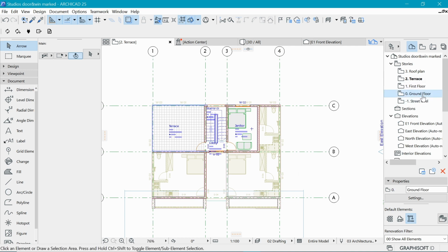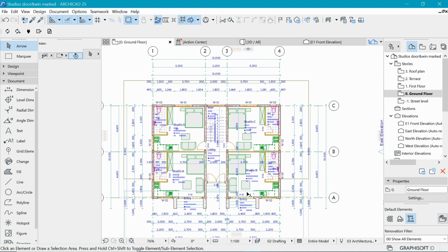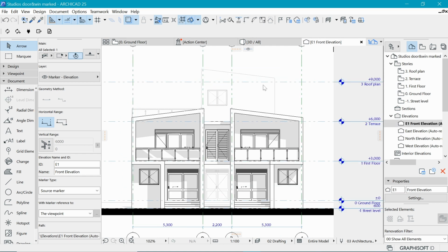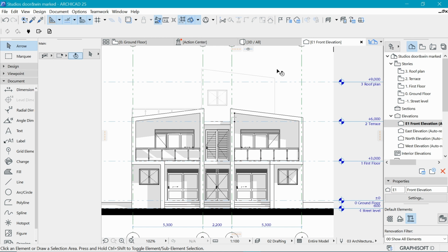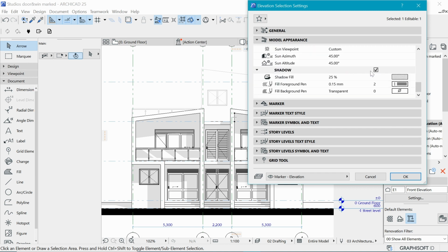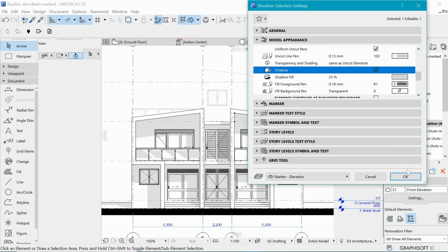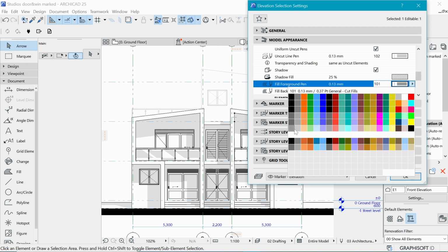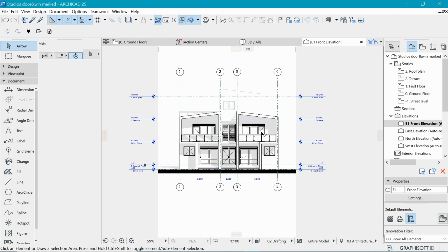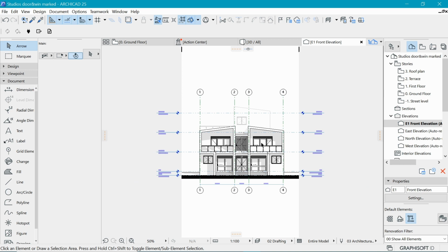Yeah, so where it is, we can see that the door on the ground floor has been left out, and we might want to take it further, this line, such that it's just after that door. Okay, but the rest of the things should be faded backward. All right, and in order to keep the consistency, I think I will put back the shadows in the faded elements. Okay, so I'm going to do that, but where is, yeah, let's keep the shadows as well, and hopefully that shadow is 25% as well. Yeah, and this time maybe a lighter color. Okay, yeah, just a little hint of the shadow. Yeah, much better. Right, so I think I like this elevation now, and it's pretty ready.